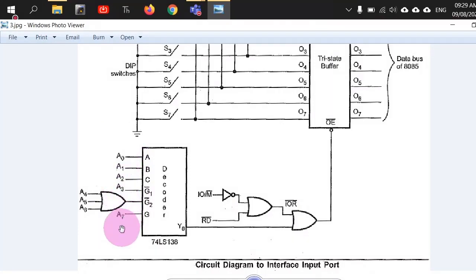And it is also important to note that A8 to A15 will contain addresses, I mean, even after your first tick of the clock, when you are trying to read something through an input-output command, because we already know that latching mechanism, we can use an external IC to be able to latch the addresses, right? So that is attached in the lower byte. So both ways, any set of the combinations can be used. So you can see that A0 to A7 are connected here.